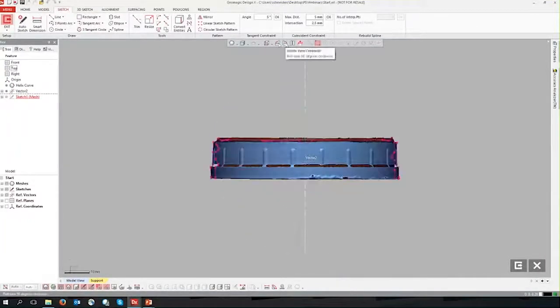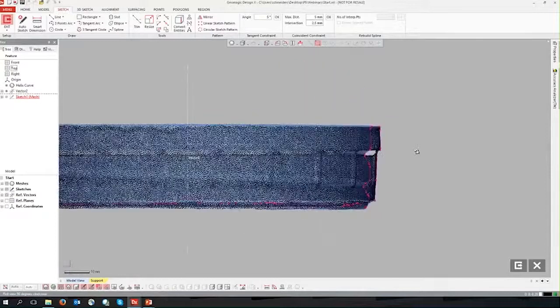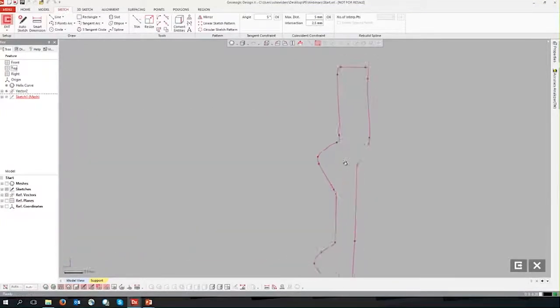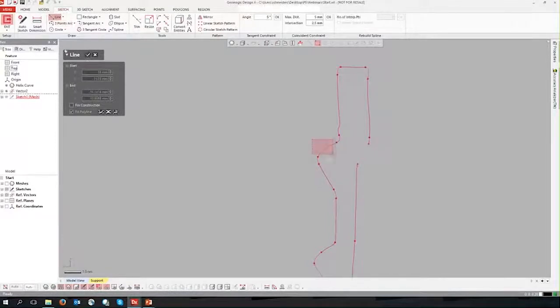And what we're going to do is we're just going to use one of these as our base sketch. So if we zoom in here, we're going to look at this top thread right here. Since, again, this is injection molded, it's not perfect. So we need to start constructing perfect sketch shapes to describe this. So we'll go ahead and just extract the top, and then we'll go ahead and extract the bottom. And we can kind of see that this is not a perfect triangle.